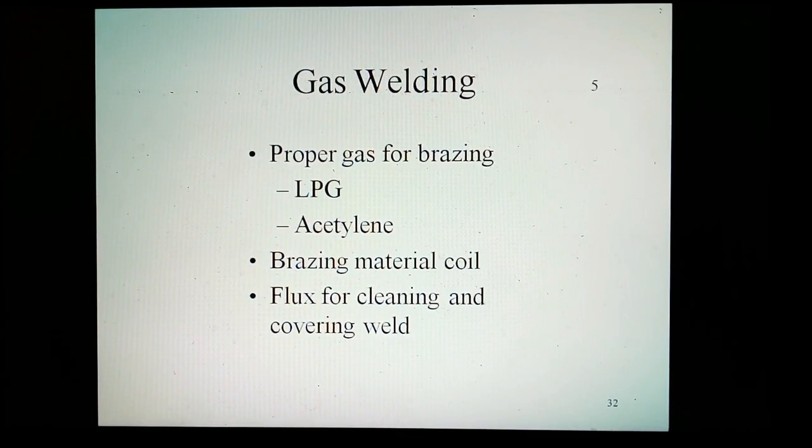Gases used for welding fuel before acetylene could be effectively produced and contained. Coal gas and hydrogen were used for gas welding. Today, gas welding is performed using LPG and acetylene. Oxyacetylene is the most common gas combination used in gas welding operations. Oxyacetylene welding combines oxygen gas and acetylene gas to create the flame. Acetylene provides the hottest flame of all gas welding fuels, and can therefore be used to weld or cut thicker materials. However, acetylene is more expensive than most welding fuel gases.